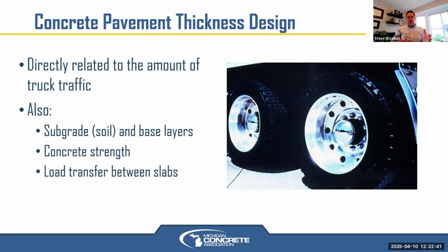But the main things you need in order to determine how thick your concrete needs to be are what's going to be on top of it and what is underneath it. Those are the two things. Once we know what's going to drive over top of it, what it's sitting on, and over how much life, how long you want it to last, then we can determine how thick, how strong, and the details of load transfer and things like that.